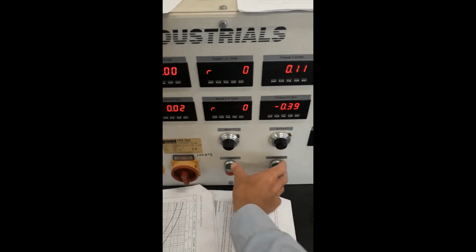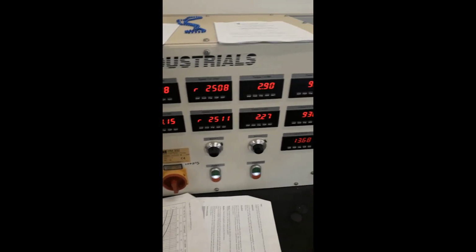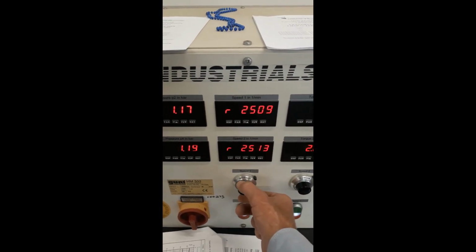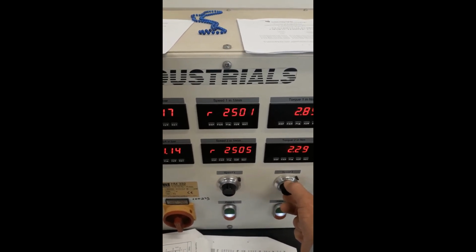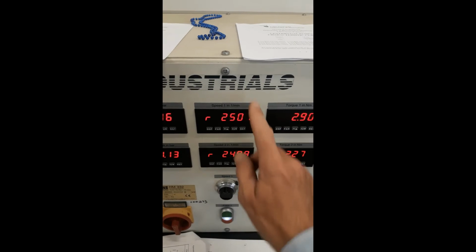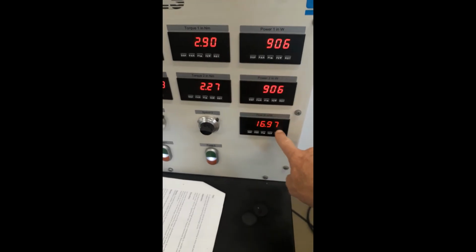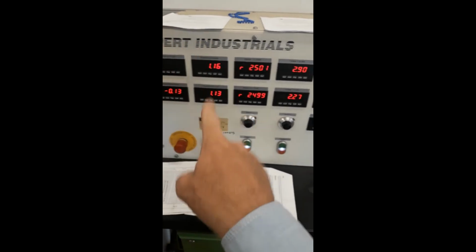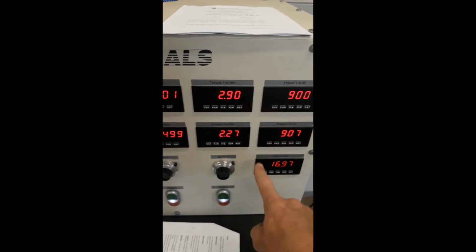Then we're going to switch on both pumps. And we're going to adjust their speeds to 2500. Again, this speed drive is very sensitive, so we try to get it as close as possible to 2500. That's close enough. And if we look at the flow value here, this is our maximum flow with our control valve fully open. So that will be our first data point, and we capture the inlet pressure, the outlet pressure, the speed, the torque, and the inlet power, and of course the flow value.